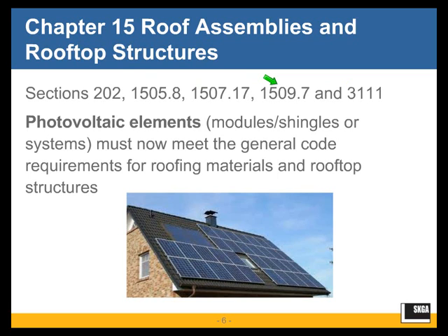But if you take a look at section 1509.7, you will see that there is a structural related provision that's new in the 2012 IBC for roof-mounted solar panels and how you would design them for wind loads, for the component and cladding loads. This is by no means a comprehensive set of provisions for the wind design of solar panels. We do refer code users to the SEOC guidelines for the wind design and seismic design of solar panels.